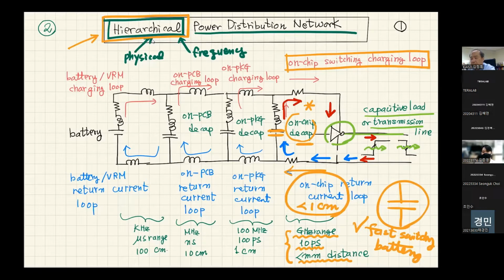Why do we have to cover probably 20 to 30% of your chip with capacitor? Because we want to have a stable power supply network inside the chip. What is the advantage of your on-chip decoupling capacitor? Because it's placed very close to your I/O switching circuit, inductance will be minimal, and you can minimize power supply circuit noise.